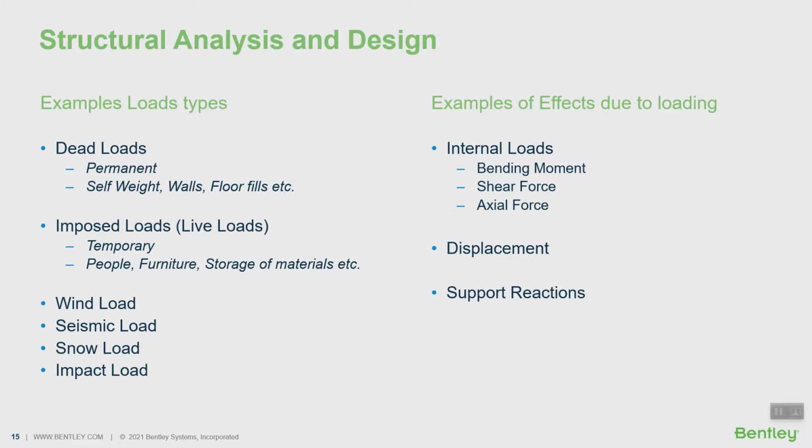While seismic loads are only applied horizontally in a typical case, for a wind load, the uplift is also very important. As discussed previously, there are also several effects on the structures due to these types of external loading, and those effects are internal loads and displacements. And then there's also another effect, which is the reactions developed at the supports. The foundations for a structure are sized and designed according to the support reactions, so these are also very important to calculate.